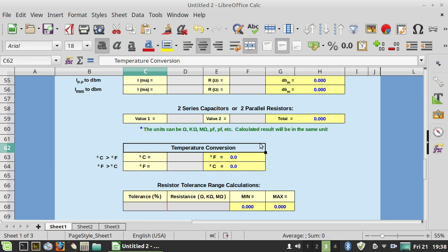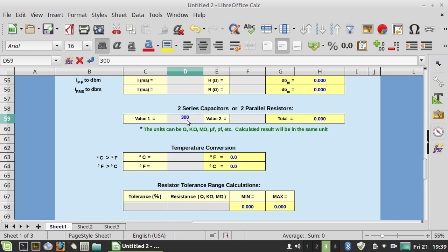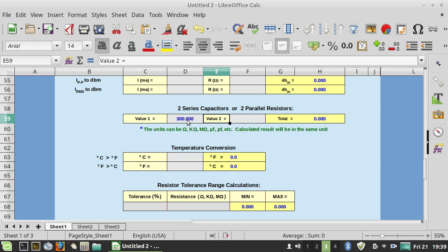I'm working on an antique All-American 5 tube type radio, and the oscillator section on the tuning condenser can't quite tune high enough. It's too high in value. Let's say that it's a 300 picofarad section on that cap. I'd like to drop it down a little bit, but what value cap to put in series with it to drop it down a little?